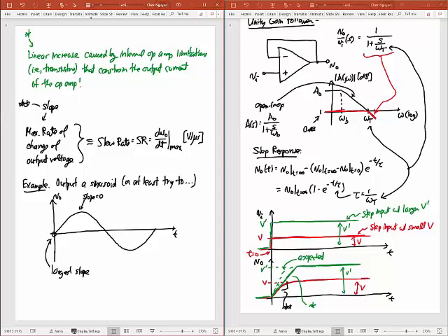So throughout a sinusoid, you have different rates of change of that voltage. And what that's going to tell you is that at different points of that sinusoid, this op-amp, if it has a slew rate limitation, will be able to keep up. At other points it cannot. Okay, so if I start my sinusoid right there, and if my op-amp has a lower slew rate than that, so say that this largest slope, which is dV_out/dt, say that's greater than my slew rate.